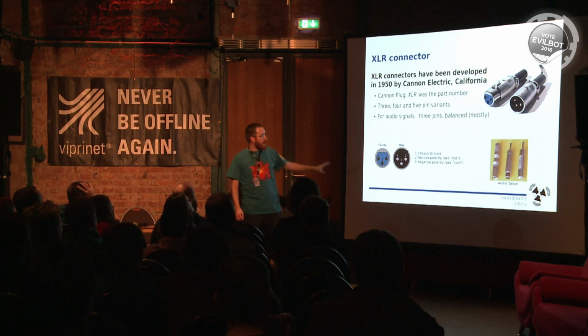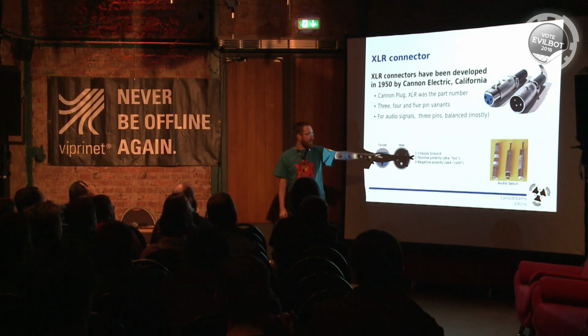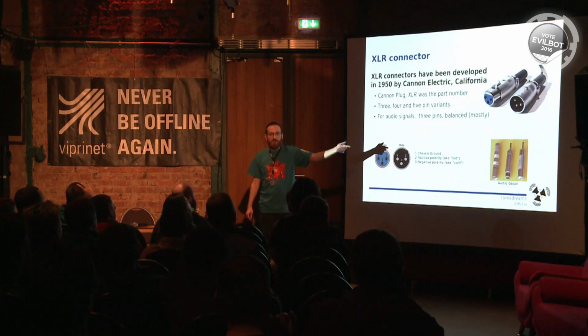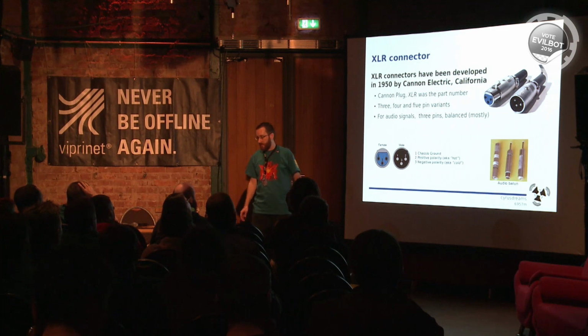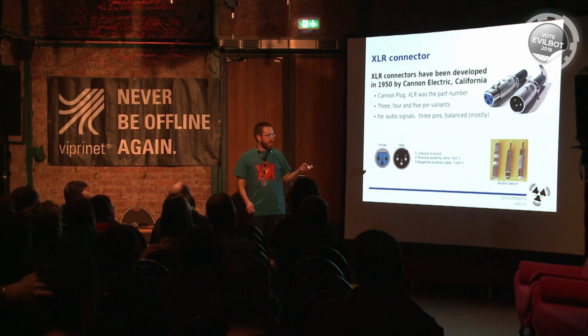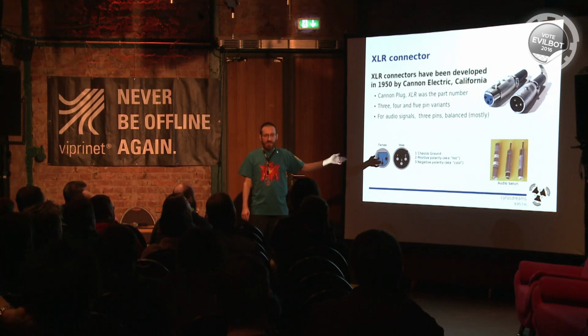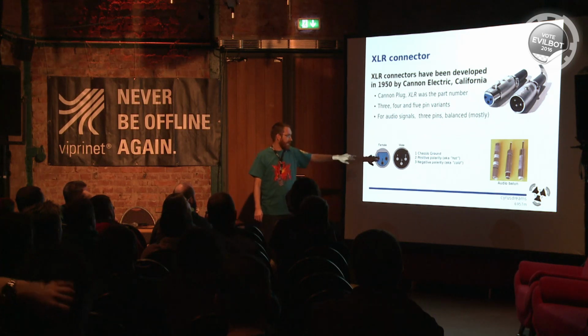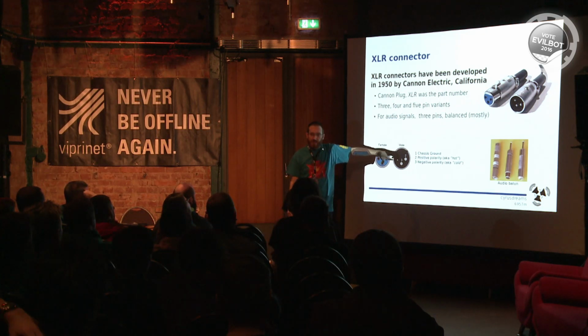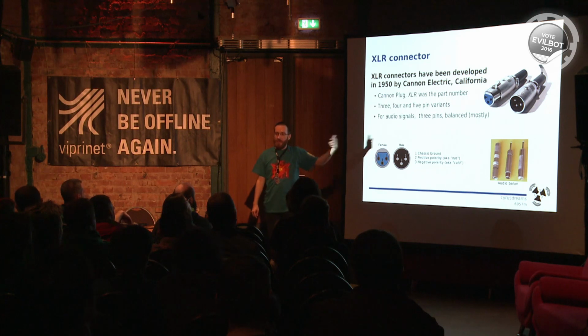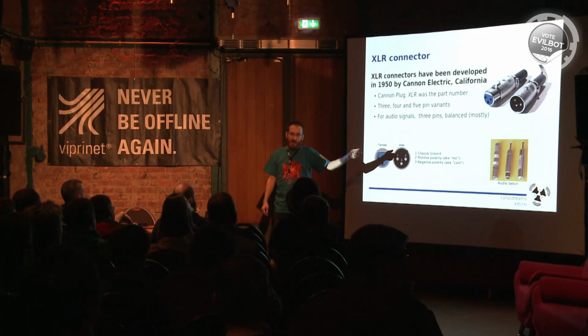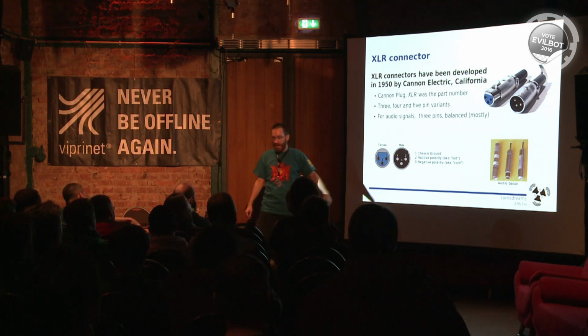And there are wired interfaces to tip and sleeve. You can do that just by wiring. A better way would be using an audio balun or a DI box to convert between those two. Because if you just wire it, you get half the signal that you normally expect, because we had this subtraction going on where the signal gets doubled. If you only use an unbalanced signal, the signal is half at the receiving end.